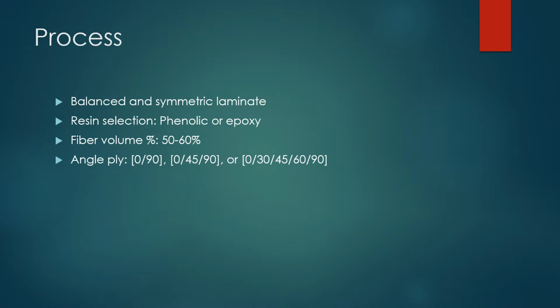We finalized these as our final two options because of research we had done into the industry. We figured that we'd settle with epoxy resin because of the higher strength it provides, and the epoxy is also found to have a lower density. Unfortunately, the epoxy is more expensive, but since this is an aerospace application, the lower density should lead to cost savings over time.